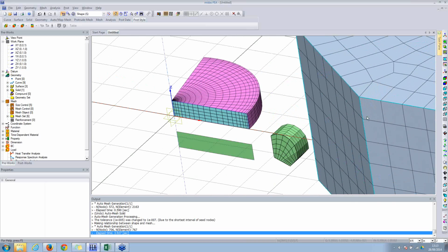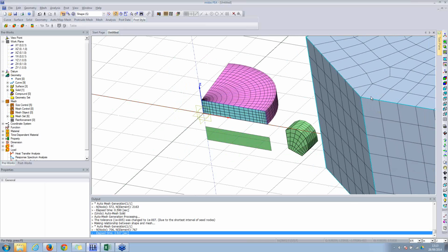So if you have one block of element, you will have some number of integration points in it, and stresses will only be calculated there. So the more integration points you have, the better average you can get, and the better contours you can get for the stresses.